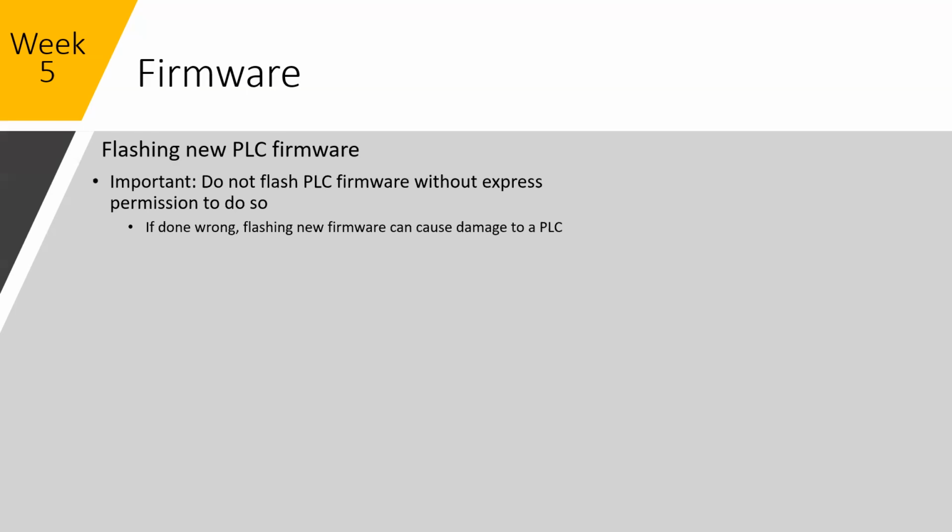They're at 32 now. They seem to be releasing a point release like every month, constantly changing, finding security fixes, adding features. So it's very important. If there's one thing you remember about flashing a PLC firmware, don't do it unless you have to. When you receive a processor, a brand new one, it's going to come with a factory tested firmware.